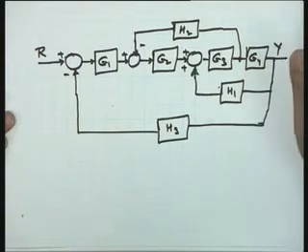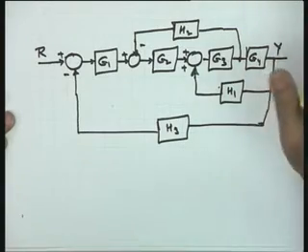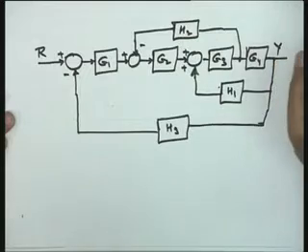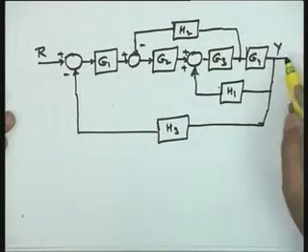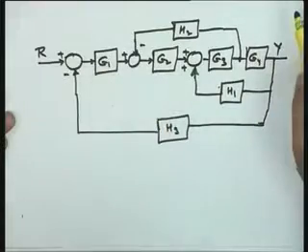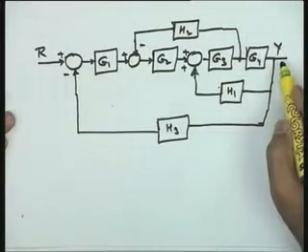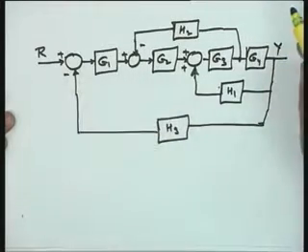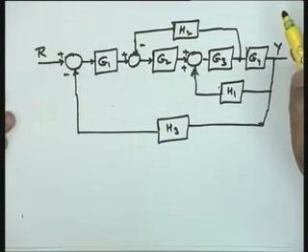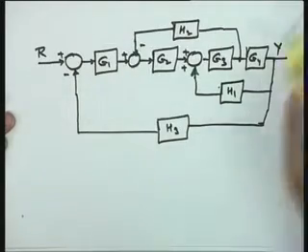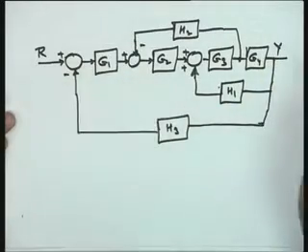At this juncture, let me not give you the corresponding physical diagram of a control system. Let me see whether by simple manipulation of this block diagram we can get the relationship between Y and R, because for the purpose of analysis I will require a transfer function between the output and the input, so that for a given input the time variation of the output could be obtained. So, for that purpose I require the relationship between Y and R.